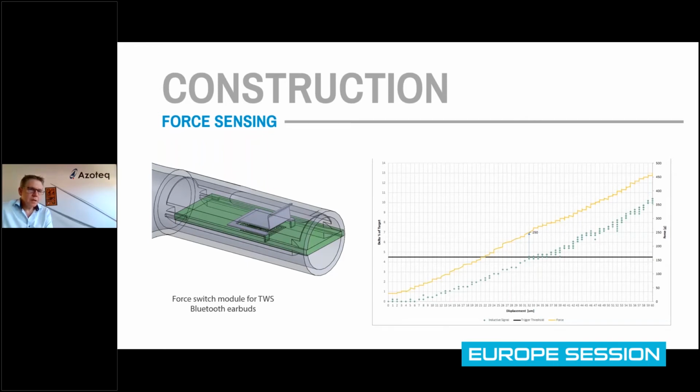If you were to use capacitive sensing for this force sensor, then water would also interfere with the capacitive sensor. So you can get false positives from water interference.